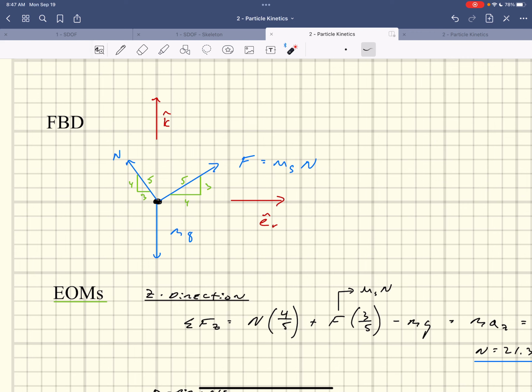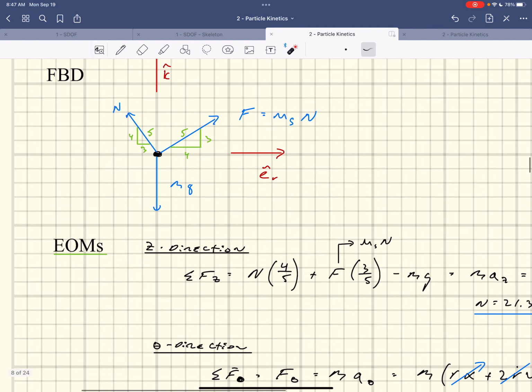Okay. Cool. And then when we went over to this direction, we were looking at in the R direction. You got that guy and that guy. It's 4/5 because that's the horizontal component over hypotenuse, and this one is 3/5 in that direction. It's a really nice trick. Like I said, when you see a 3, 4, 5, or where I give you all the, you'd be like, yes, I know how to use that. What you knew right away the normal was,